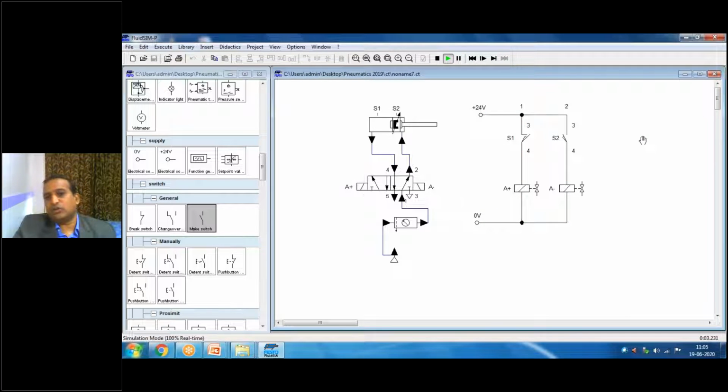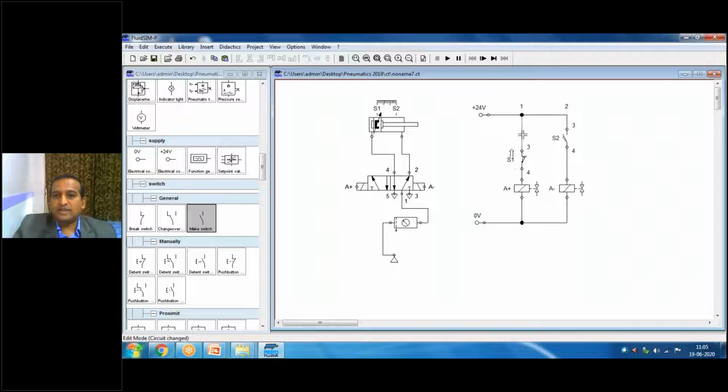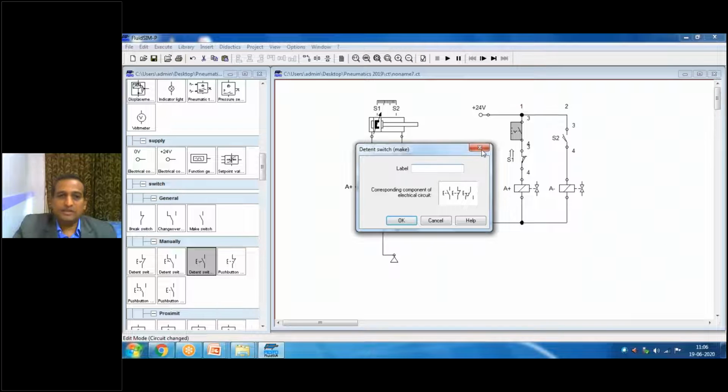Then at the end of the piston, the sensor, now full stroke. Automatically, this is industrial automation or mechatronics. So everything you can use with one master control in your hand. Suppose I need one master control. Suppose I can mention here the start button, that is called a momentary switch. Unless you start this switch or make it on, the system is not on.